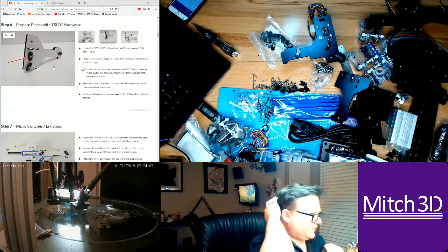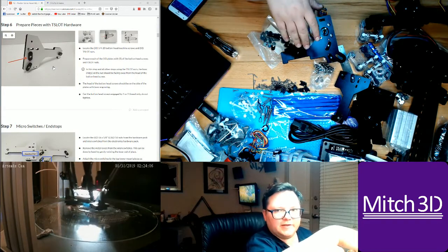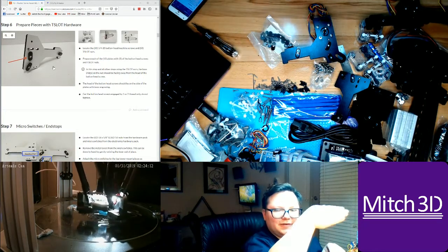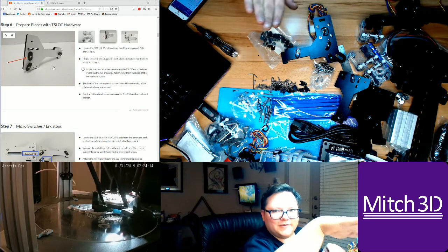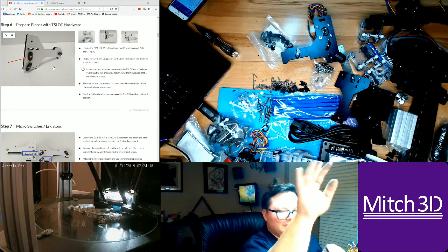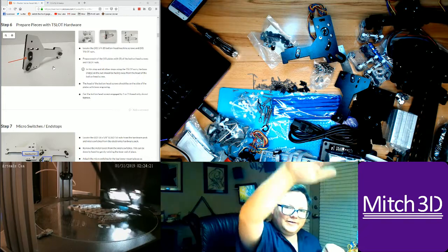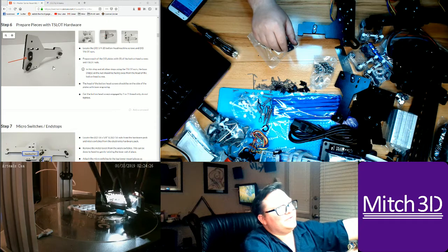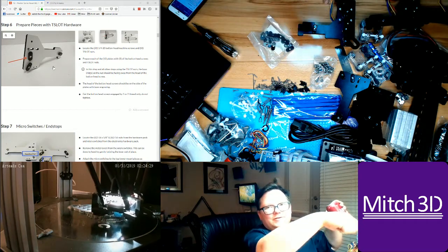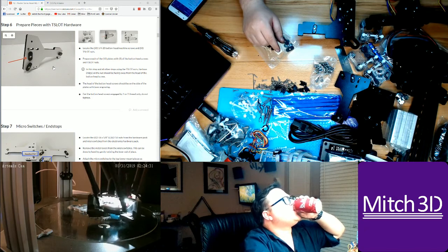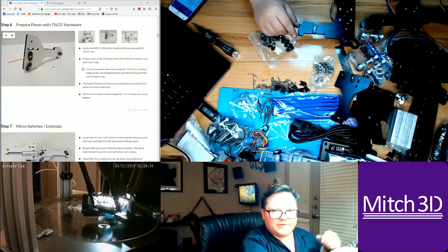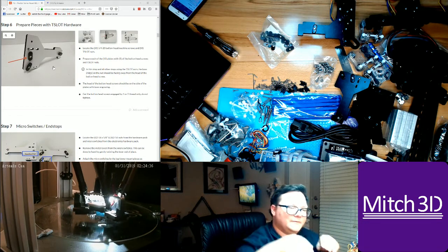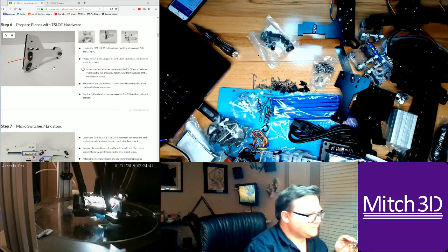Each of the towers has to be as smooth as possible, so that you're not catching on one tower, or else one arm will start drifting, and all your prints are going to look like this after a while. Each layer is just going to keep progressively shifting on an arc on one of the towers, so you can actually see which tower failed by watching where the skew is. But layer shifts still happen too, where it shifts ever so slightly, so you have a little bit of a raised bump, but it's not as noticeable as on a Cartesian printer.